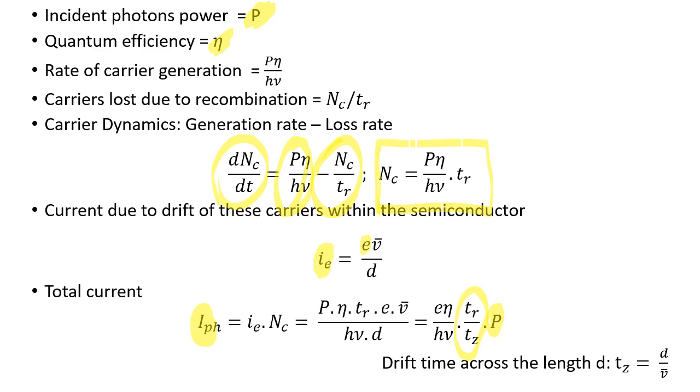So maintaining it to be charge neutral is going to draw in more electrons for the same electron that had actually gone out of the circuit, right? So this kind of thing is what is generating a sort of gain in the system, where you are creating more charge carriers for that single photon that came in, right? So that is why there is a gain term associated with that.